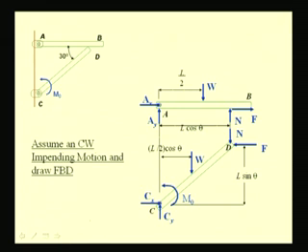We know that we are interested to find these frictional forces that exist when the rod impends to move and the required moment. So, we can take the force summation and moment summation equations, and for the impending case relate this F with this N using this equation.